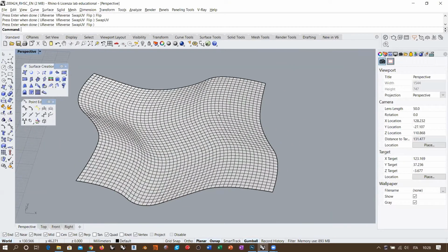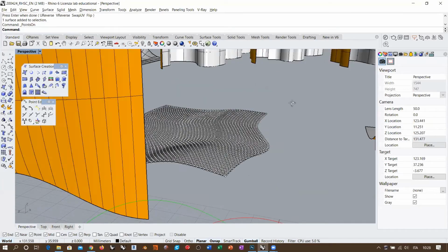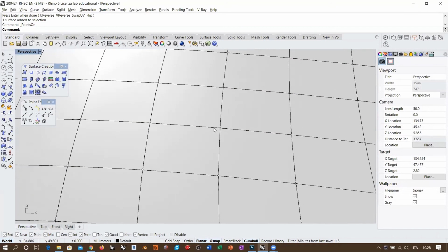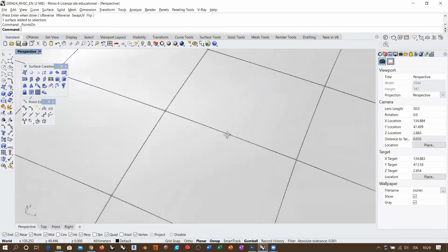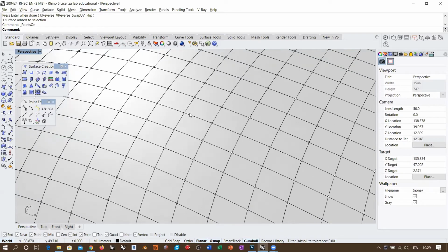And now what I can do with this, in order to create a bulge in this area, the more efficient way is to use the soft move command, because take a look at how many control points we have here. The topology is so dense that the control points start to be coincident with the knot lines, okay? Because they are evenly distributed, there is a uniform knot vector, so there is this apparent correspondence. Take a look that the control points never lie on a knot line, or isocurve, as you might want to call it. They are always on the outside of the curves, because there is no internal discontinuity, no kink in this case.